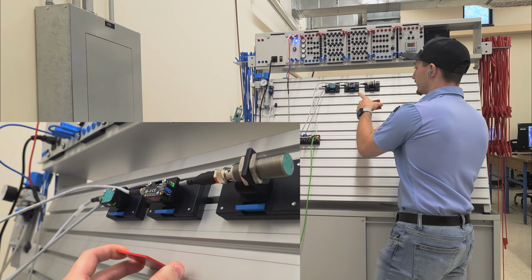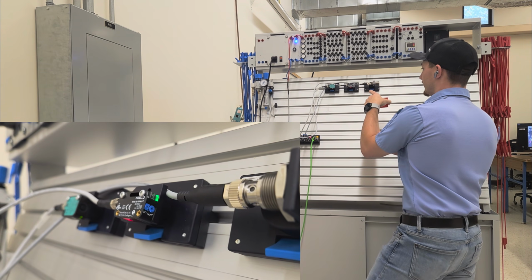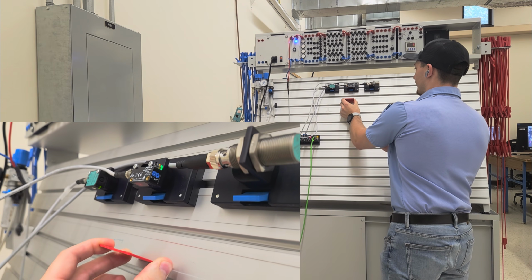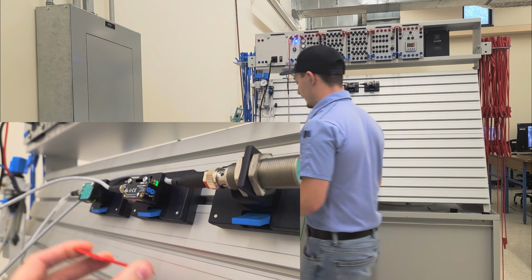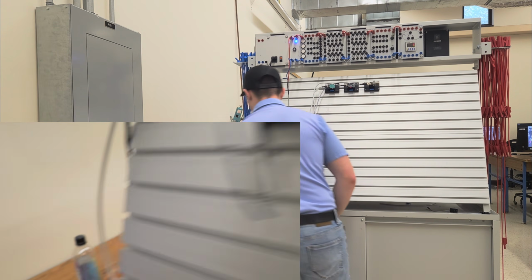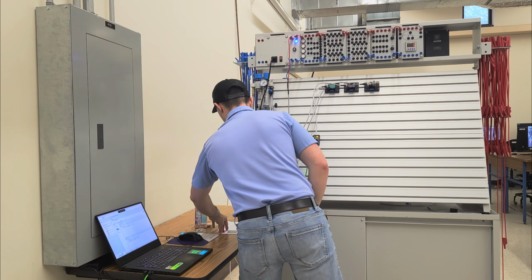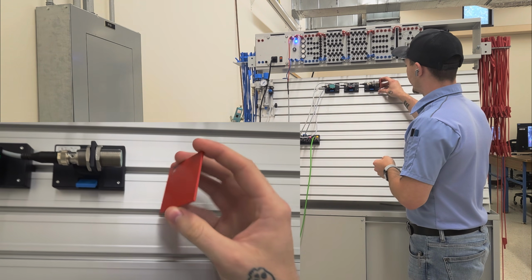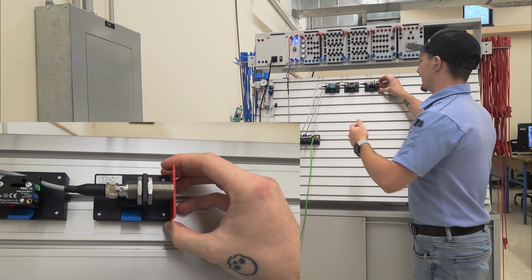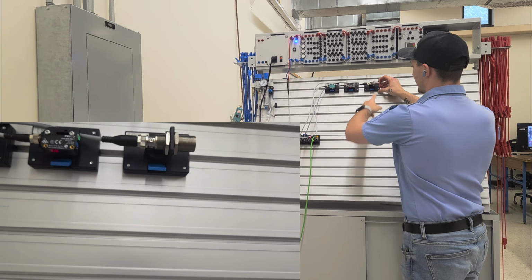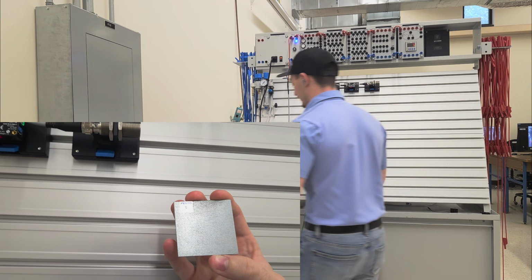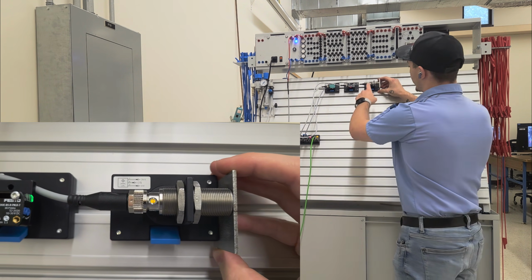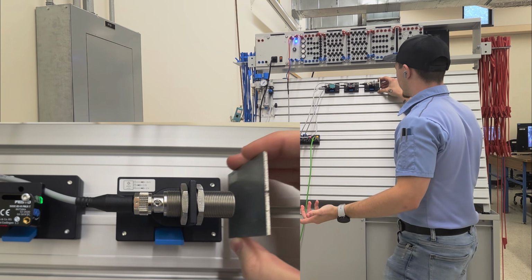Same thing with the diffuse light sensor. You can see it's blinking green, that means it's communicating. Put this in front of it, and the orange light in the middle comes on. Now I'm going to do the inductive type sensor, and we'll keep the red block, the plastic. Put this in front of it, and this is the light that it's supposed to be lighting up, and nothing's on. But let me get the piece of metal and put that in front of it. Now you can see that indicator light is saying, okay, I'm reading something.